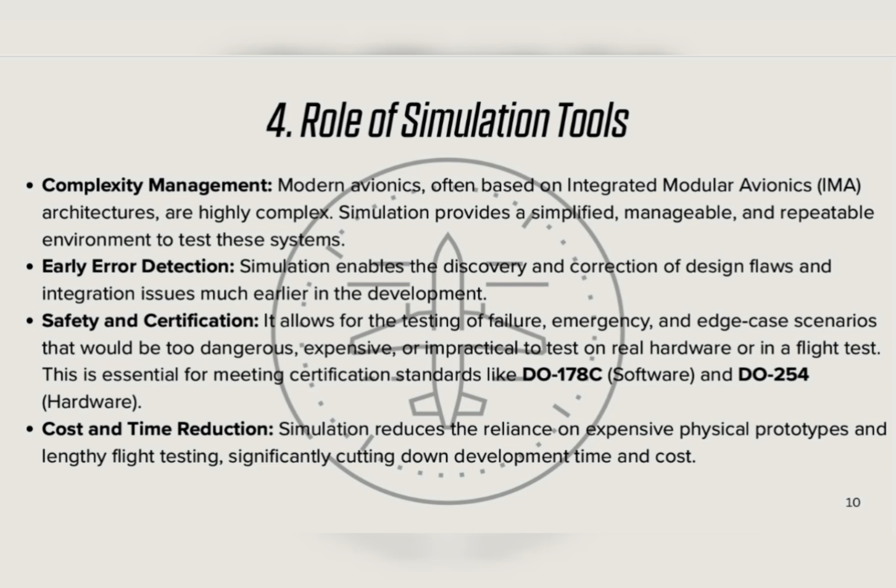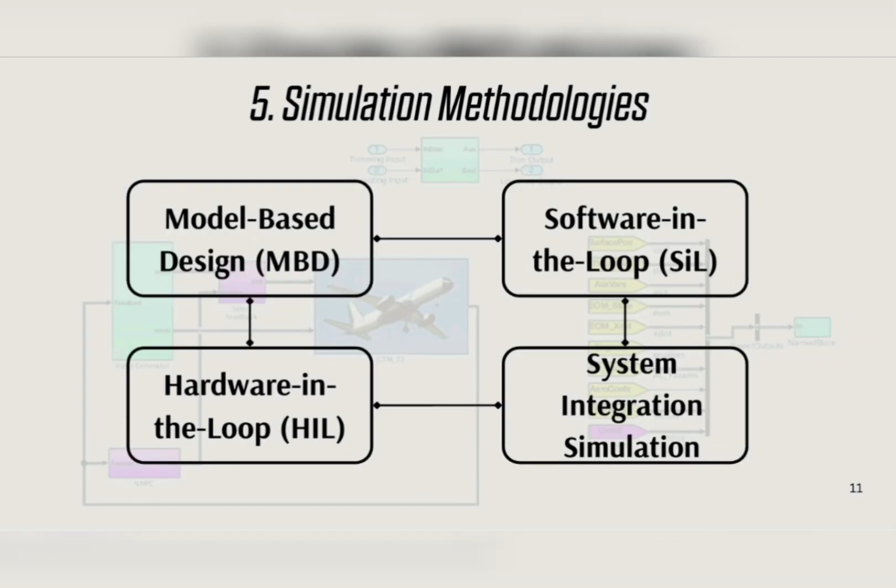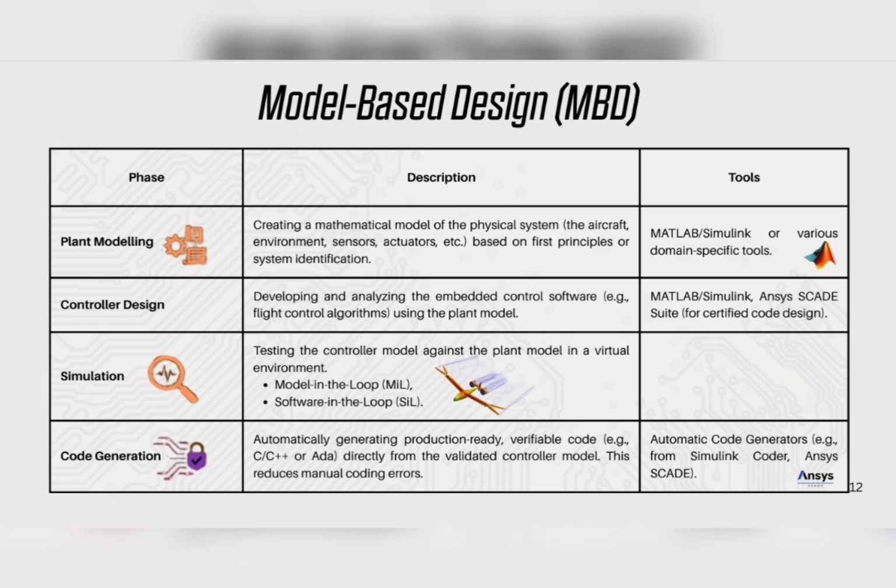Simulation reduces cost and time by substituting expensive prototypes and flight hours with repeatable virtual tests. Now let's dig into each simulation fidelity and what it's used for. Model-in-the-loop, MIL. It validates algorithm correctness inside the modeling environment. This step is about functional correctness before any compilation.